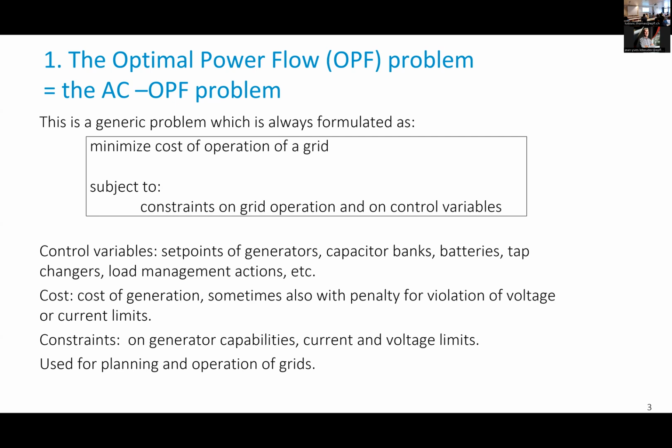You may have the converse problem if you have a lot of loads. For example, electric vehicles may be very large loads. When they get connected to the grid and they all pump energy at the same time, that may cause undervoltage. That needs to be taken care of. That can be taken care of by, for example, having batteries in the grid that will inject more power at the time where the electric vehicles are using it, or absorb more power at the times where the solar panels are generating in excess. Those are examples of operation of a grid.